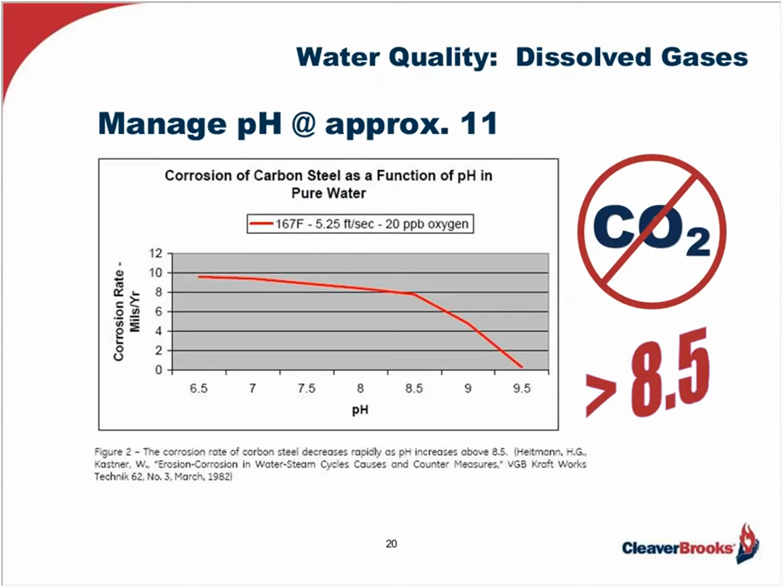Carbon dioxide will form in the boiler's feed tank as the water is heated. And as shown in the slide before, the amount of CO2 formation is dependent upon the amount of carbonates in the feed water, especially bicarbonate. The other factor with CO2 and carbonic acid attack is maintaining the proper pH level in the feed water tank and the boiler.